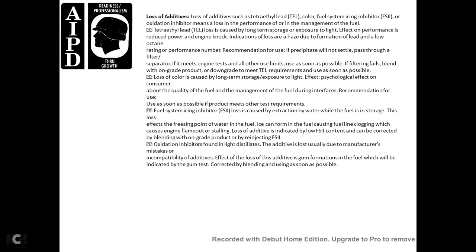Loss of additives such as tetraethyl lead, fuel system icing inhibitor, or the oxidation inhibitor means the loss of performance of the fuel. The tetraethyl lead loss is caused by long-term storage and exposure to light. The effect on performance is reduced power and engine knock. An indication of the loss is low octane rating performance. Recommendations for use: if imperceptible, let settle and pass through the filter separator. It means the engine tests are within limits, so use it as soon as possible. If filtering fails, blend with on-grade product, downgraded to meet the tetraethyl lead requirements, as soon as possible.